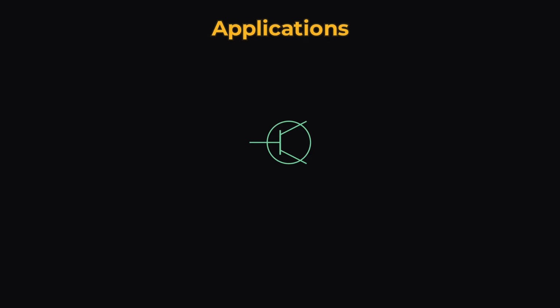The fourth job is amplification and switching. A bipolar transistor is two PN junctions placed back to back. Everything in this lesson is therefore the foundation of amplifiers and logic. A fifth job reuses the breakdown region. A Zener reference holds a stable voltage by operating in controlled breakdown. The mechanism from the previous beat becomes a design tool.